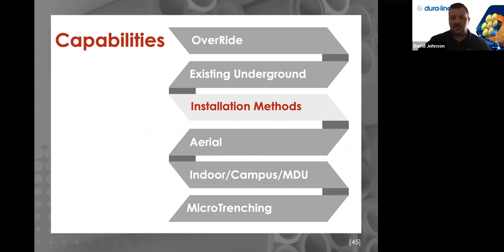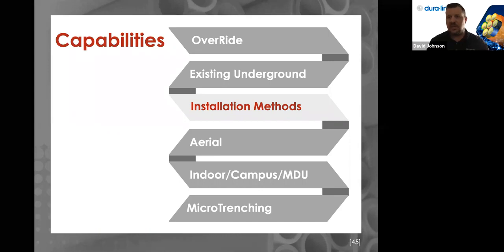After you've done that, you turn the air off, you stop the machine, and then you work your way back to access point 2, and you simply uncouple that microduct, and then you turn the air back on, make the fiber float, and then you start jetting in your 100 feet of slack loop at access point 2. Then you have your 100 feet of slack there. Then you stop the machine, stop the air, go back to access point 1, uncouple that coupler, and do the same thing. Put the air on, float the fiber, and put in another 100 feet of slack loop.